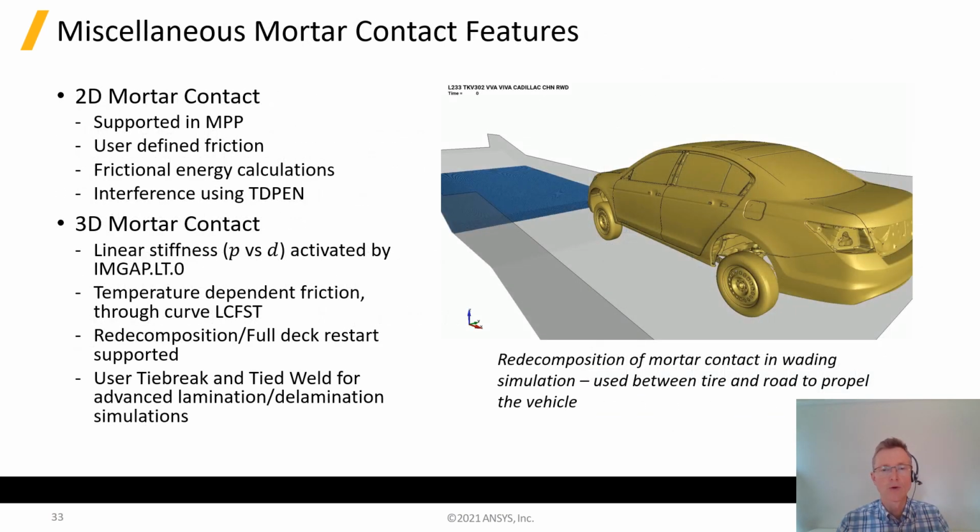The so-called mortar contact has a more physically correct way of distributing contact forces between the contacting elements. It's essential in many implicit analyses, but can also be used in explicit and may be especially helpful in models with larger time steps like this one. There have been a number of improvements in this feature, which I won't read out, but the main thing is it gives us a chance to play this rather cool video.